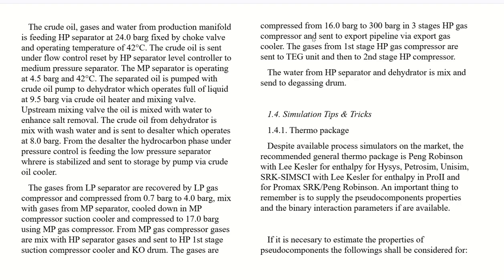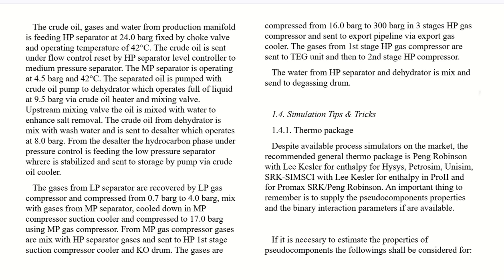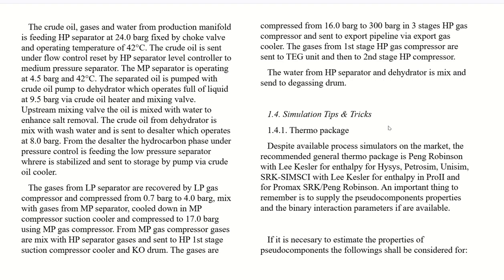Basically, we are talking about some key points on how the oil and the gas are processed. Then simulation tips and tricks: despite the available process simulators in the market, the recommended general thermo package is Peng Robinson with Lee Kesler for enthalpy. For HYSYS, Petrosim, and Unisim, SRK with Lee Kesler for enthalpy, for Pro II, and for ProMax, SRK or Peng Robinson.